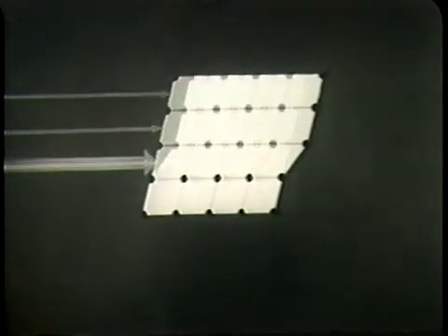In the process of twinning, the lattice is deformed by some fraction of an atomic spacing. In slip displacement, the blocks of atoms move an integral number of atomic spacings. When the external force is removed, the atoms are so far from their original positions that they cannot return. Plastic deformation is the basic process underlying the strengthening and hardening of aluminum alloys through cold working. If the force had been increased beyond the metal's ultimate strength, the crystal would have been sheared or ruptured.